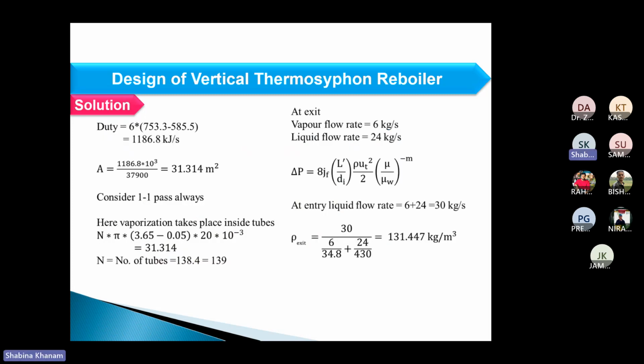So, you keep on seeing the steps which are involved in design of thermosiphon reboiler. The first one is to calculate heat duty. Okay, this is not the first step only for this reboiler. For every heat transfer unit, the first step is to calculate duty.